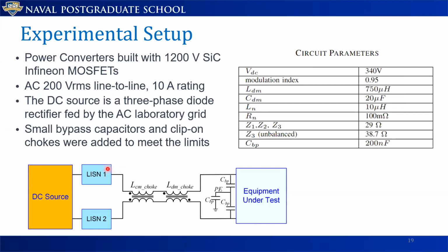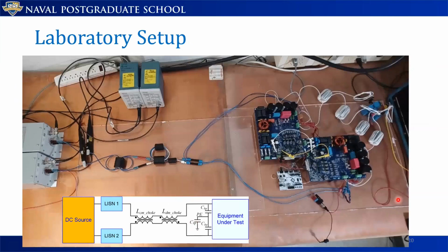So what I said, no common mode choke. In reality, when we go in the lab, because we are not modeling for the very high frequency EMI, we needed to put some small clip-on chokes. These are tiny, of the order of magnitude much smaller than a typical common mode choke. So let me show what I'm talking about here. This is the setup. We use two Infineon 3-phase motor drive boards, and we took 2 legs from each one of them. And here is our control board. So in lieu of a large common mode choke, we had some small clip-on common mode and differential mode chokes.